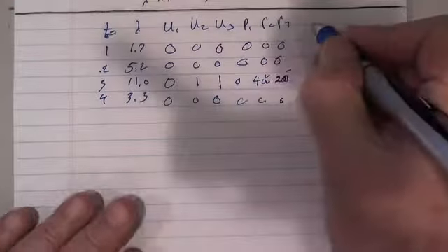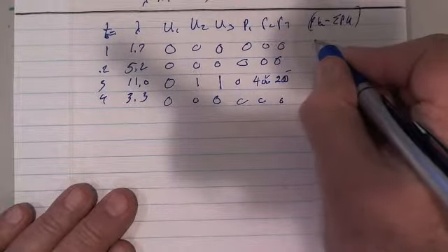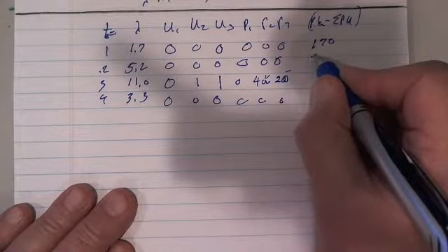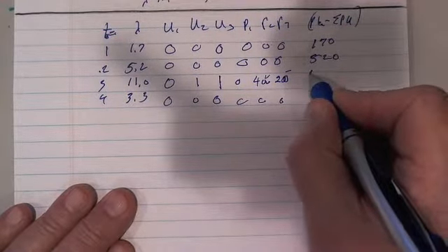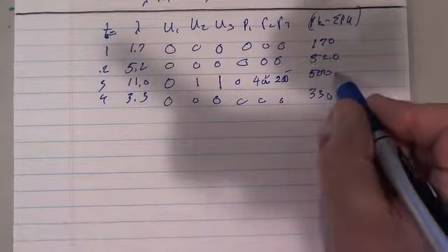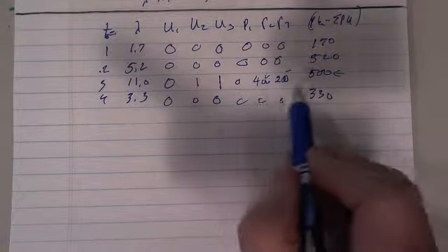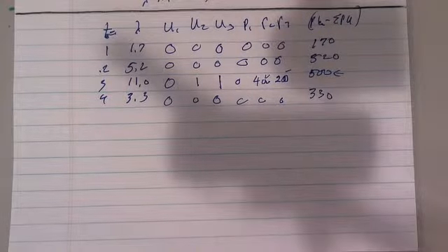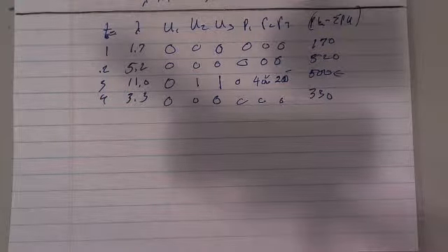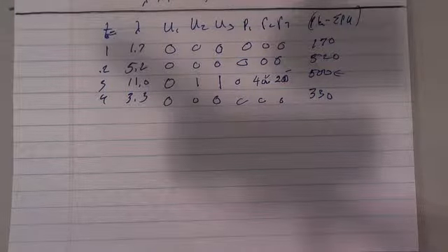And now when I do this P load minus the sum of P times U, this stays at 170, this becomes 520. Now this goes down to 500. That gap starts to get closed, 330. So this number has changed. I still can't do an economic dispatch because I don't have enough generation on to meet the 1100 megawatt load. So I'm still at 4,000, etc. And yet the Q variable starts to change. So it shows you each iteration in the textbook.